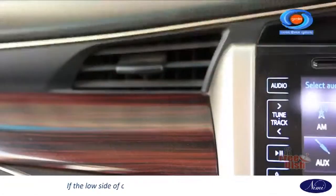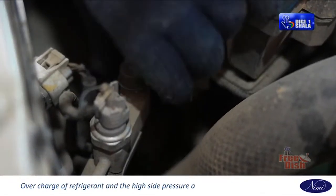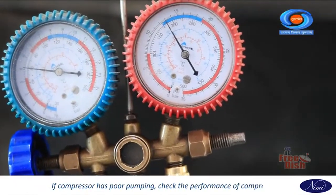If the low side of the car AC system is higher than normal, check for overcharge of refrigerant, and the high side pressure also becomes higher than normal. If the compressor has poor pumping, check the performance of the compressor.